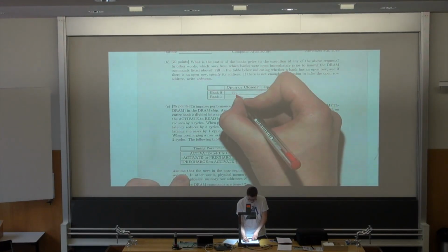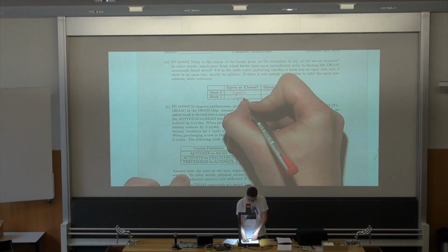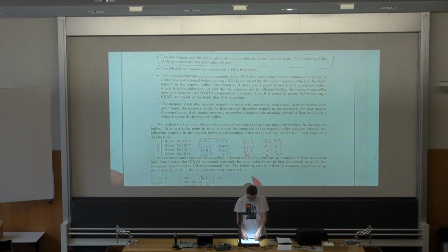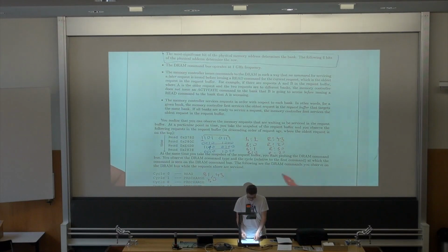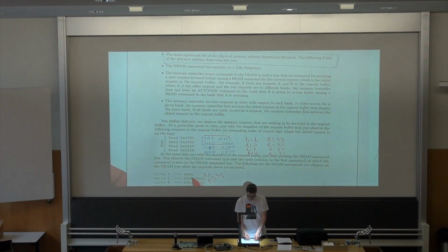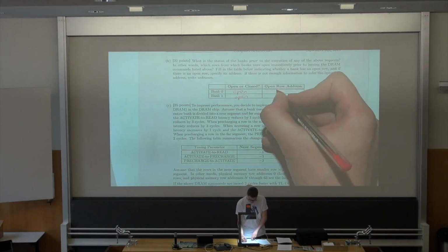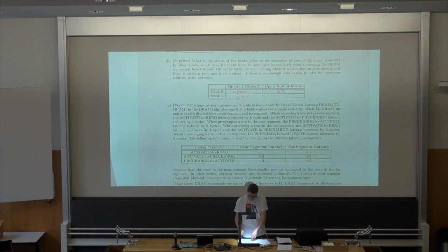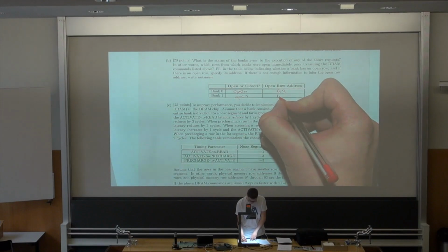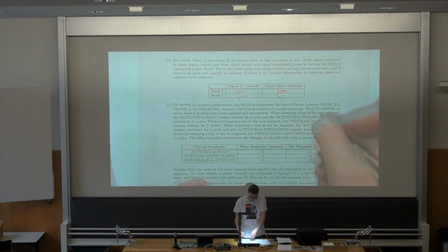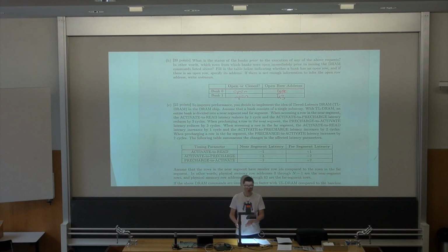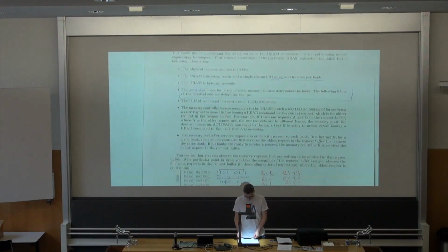So we know that both rows are open, because for bank 0 we had to precharge the row, and for bank 1 we serviced the read request, right? So the initial state is open for both, but bank 1 was 43, and for bank 0 we don't know which one. The only thing we know is it wasn't row 20, right? Okay.